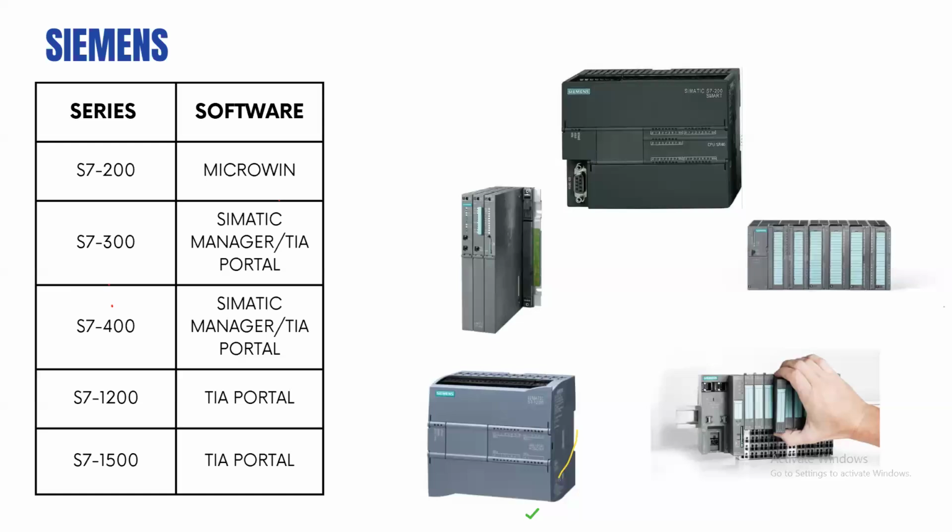Okay, thank you. Next question is, does this imply that the VFD can operate and be programmed independently without using PLC communication? Yes, it can. In fact, in many cases, we are talking about PLCs and all this. If you go to a lot of places in Nigeria, they just want to use a push button to start their machine, and when they want to stop, they stop. And if they are trying to vary the speed, they will just use the potentiometer on the body of the VFD. So in some cases, some people don't care about automation.